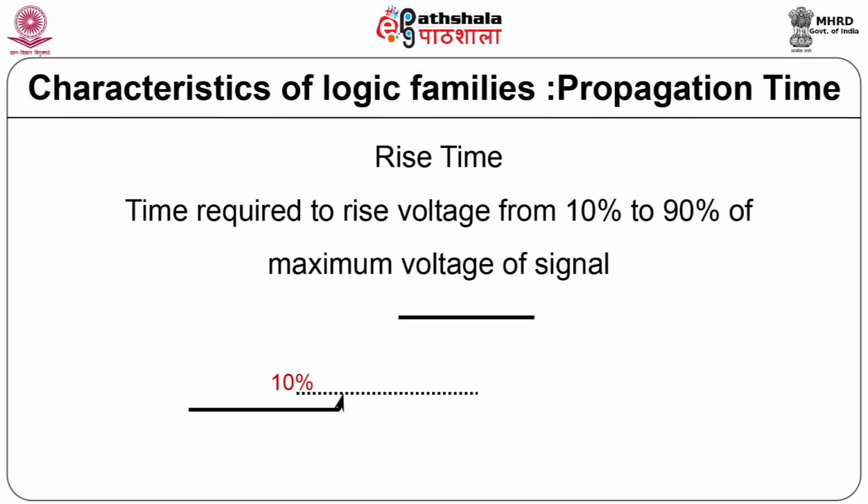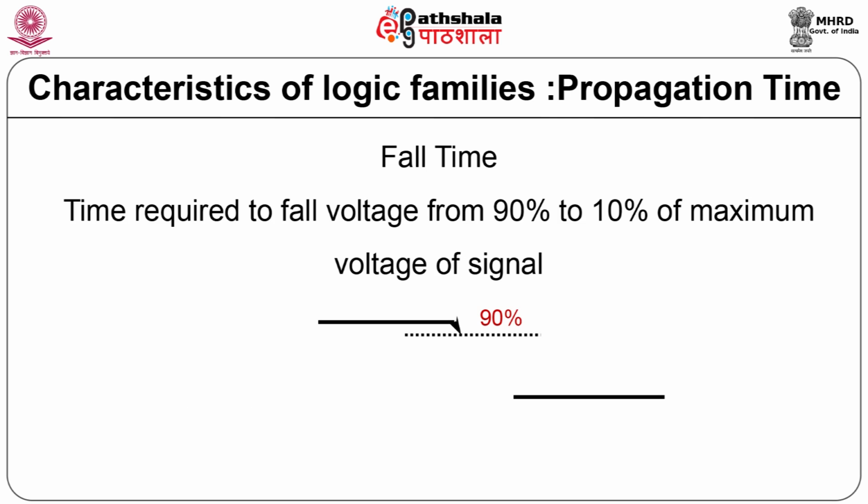Rise time is defined as the time required to rise the voltage from 10% to 90% of the maximum voltage of the signal. Fall time is referred to as the time required to fall the voltage from 90% to 10% of the maximum voltage of the signal.